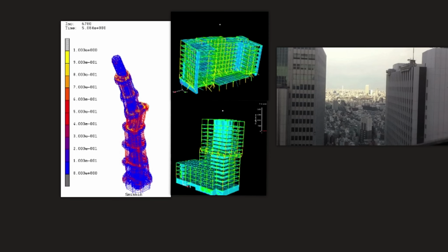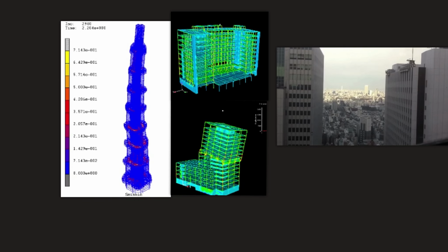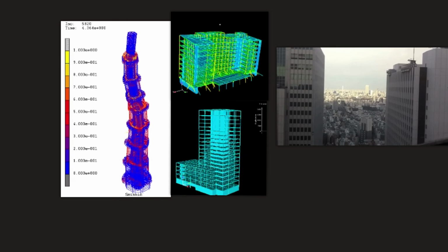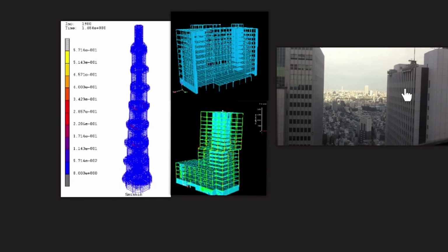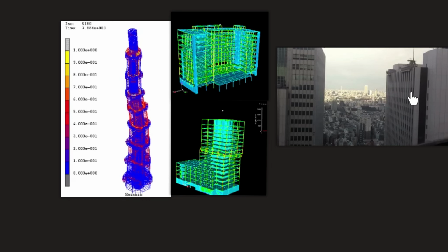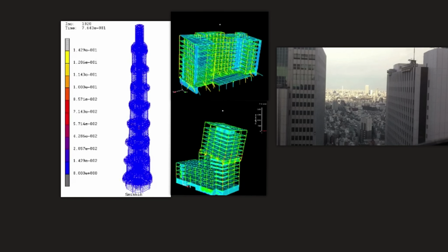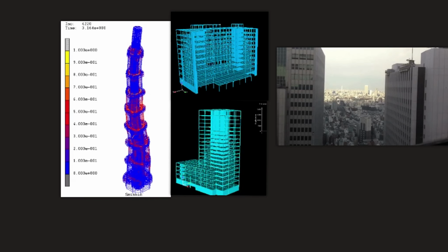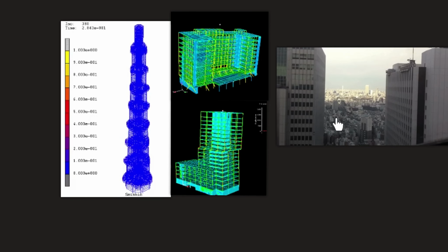But whatever different types of damping we have discussed in the earlier portion of this video, all of them will be present here. For example, material damping will be present because the building is made up of different materials. Inside the material, deformations will happen, and that will eventually result in the loss of some amount of energy. Then there are mechanical connections, there are bolted joints, there are riveted joints, so it will result in structural damping or Coulomb damping.